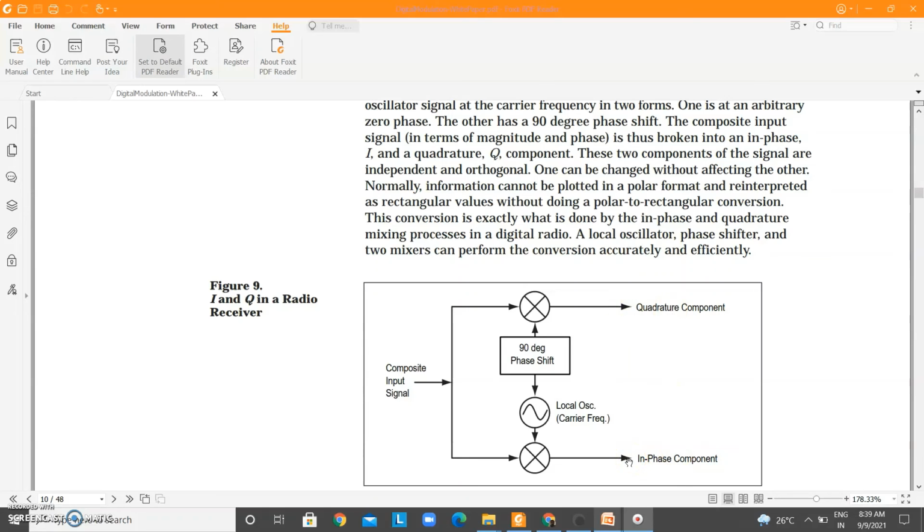Then what we do is look at the output we get for the I value and Q value, whether it is greater than a particular threshold or not. If it is greater than the particular threshold, we decide what it represents, whether it represents 0 or 1, or whether we are sending 2 bits together, dibit, then it will be whether it is 0 0 or 0 1 or 1 0 and 1 1 and so on. So this is the decision making block.